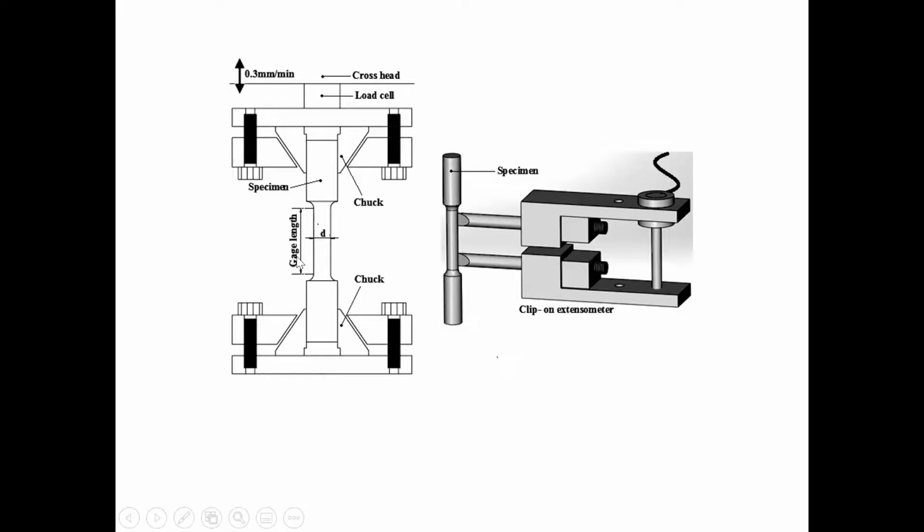And here I've specifically marked the gauge length. The gauge length is quite literally the distance between the two indicators on the clip extensometer. So we have a top monitor and a lower monitor. They're usually metal forks that just touch the surface of the sample and they move with the sample. So if the sample stretches, this will stretch with it. In fact, it'll bend, to be more precise. And it'll measure very accurately the elongation, in other words, how much we stretch the sample by.